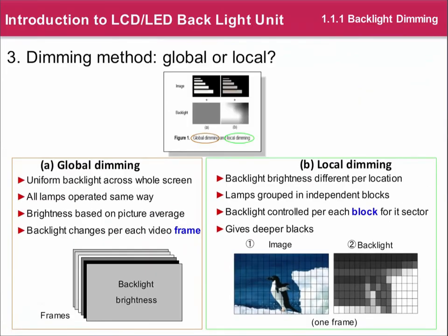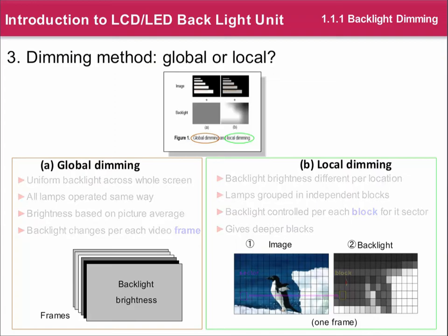The LED backlight is made up of thousands of small LEDs. Dimming is done by controlling the brightness of small groups of LEDs called LED blocks. These blocks are working independently. Each block sits behind one segment of the screen. The TV calculates how much light each LED block must produce to display the segment correctly. Because we can dim or even turn the LED off, we can display much deeper dark segments than with old constant backlight that constantly runs at full intensity.